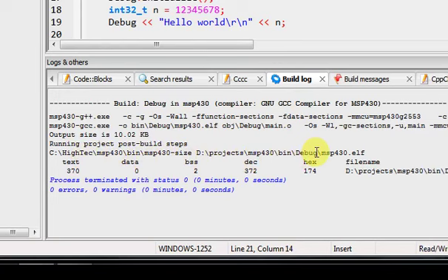post-build step. Now the reason why I'm doing this, you can do it for whatever reason you want, just to look at the pretty text or whatever, but if you take a look at that ELF file on the file system, you're going to see a file that's about 9 to 10 kilobytes. Obviously, assuming that were the case, that's going to take up a good bit of the code space on the MSP430. But luckily for us, that isn't the case. That's why we're using MSP430 size here.